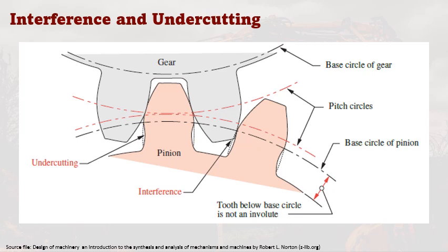So we have here an undercut tooth, when we extend the involute below the base circle, since this circle here represents the base circle. This undercutting weakens the tooth by removing material at its root. The maximum moment and maximum shear from the tooth loaded as a cantilever beam both occur in this region. Severe undercutting will promote early tooth failure. That's why it must also be avoided.